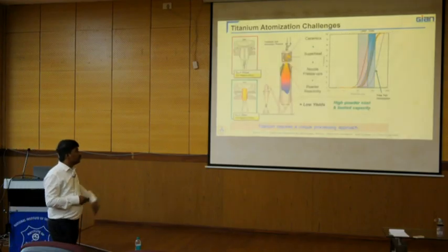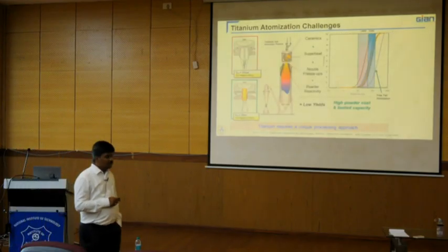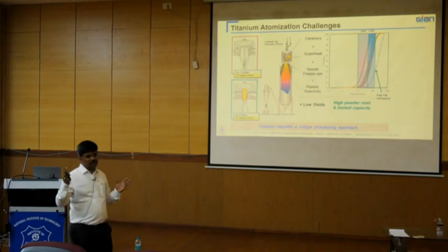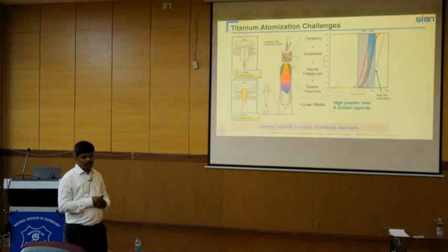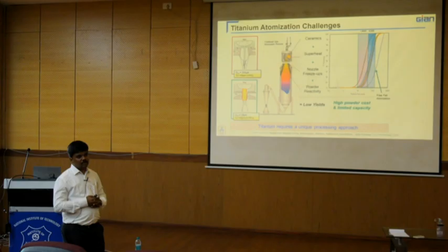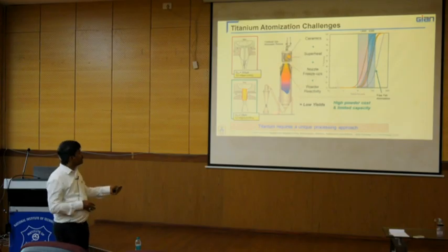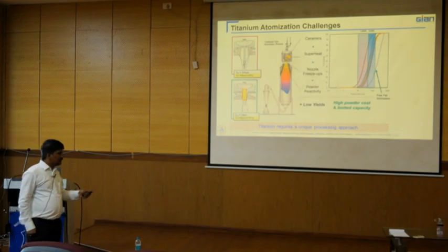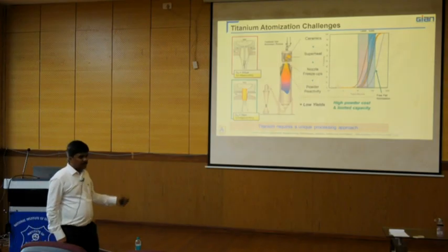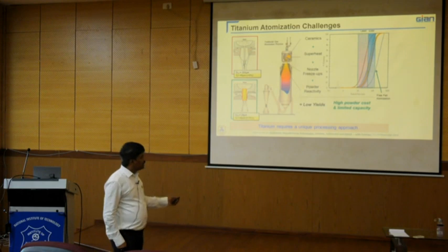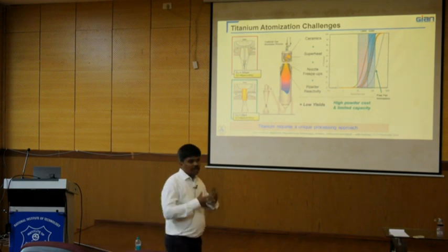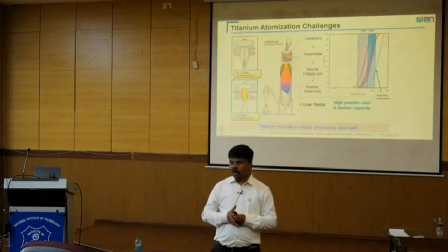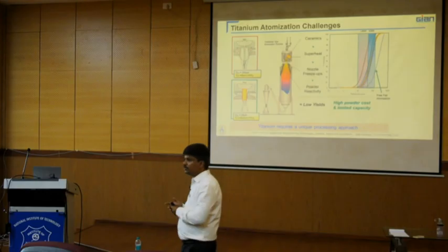But the cost of manufacturing with this plasma atomization is going to be very high, because we need to maintain the plasma channel as well as the complete atomization chamber. Especially these plasma atomizers we are using for titanium powder particles, which will have very low yielding capacity. Because do you think, to get 1 kg of titanium powders, how many tons of metal we need to melt?